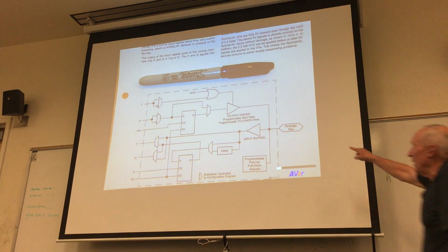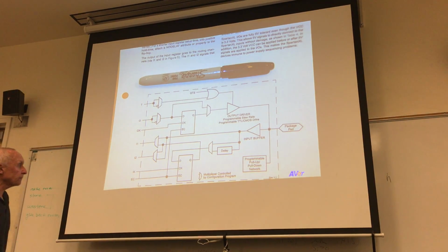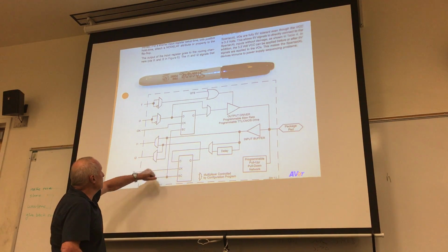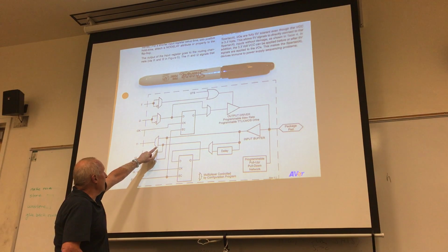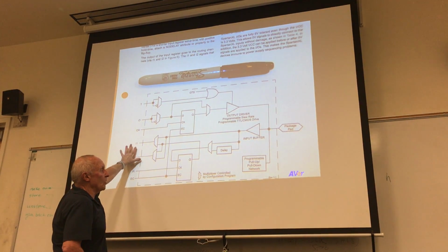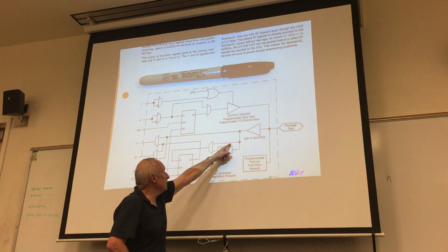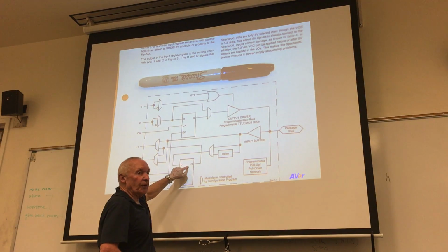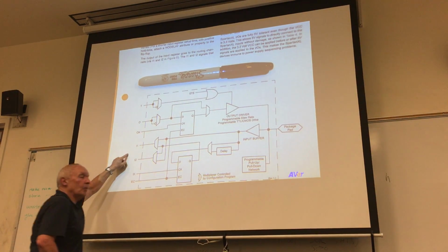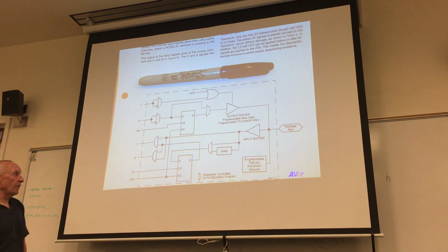This package pad is a pin on the FPGA. You have an input buffer, and this can go directly in for a combination logic input. Or you can register the input and have that go into the configurable logic block, the FPGA fabric.